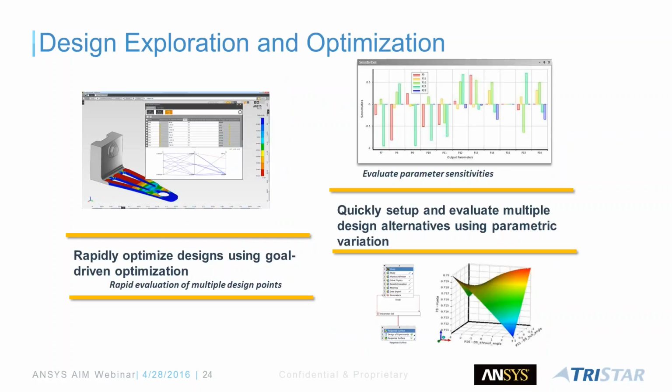And the most important thing as an engineer or designer that's currently working on your CAD system, which could be Creo Parametric, you want to see how to make design changes within your tool and propagate that to the analyses. And like I said, that's done using the parameterize option, where you are essentially exposing your dimensions and then using those design checkpoints, running a few scenarios here, and it's going to give you the results for those. So it helps you make some engineering decisions based on these, right? Rather than doing a trial and error, you're using the simulation results to help you with your design process upfront.